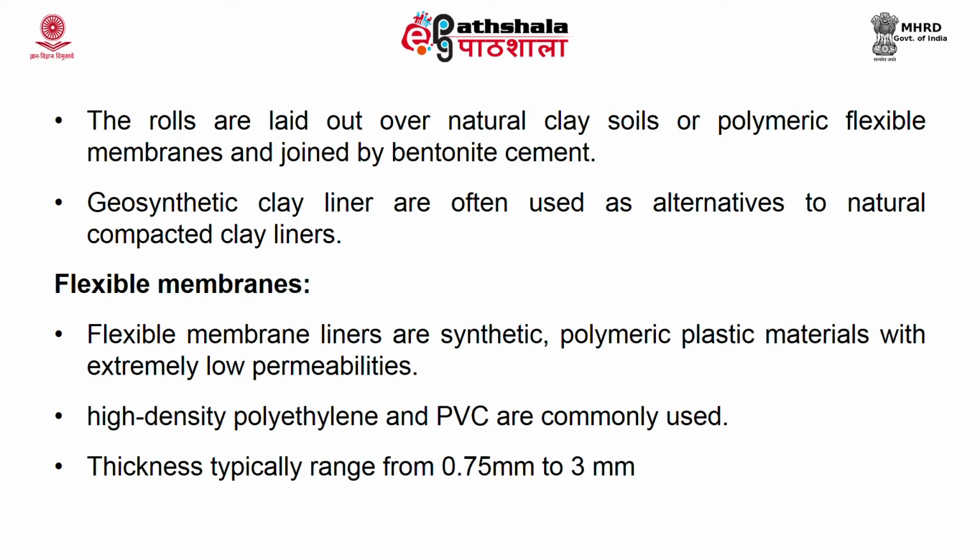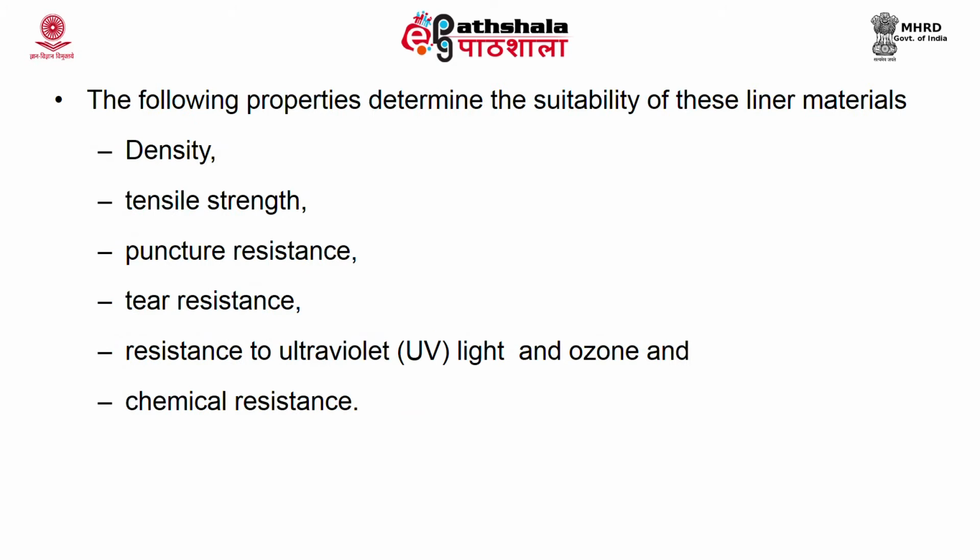The thickness will range from 0.75 mm to 3 mm. The properties which determine the suitability of these liners are density, tensile strength, puncture resistance, tear resistance. It should be resistant to UV and ozone and other chemicals.